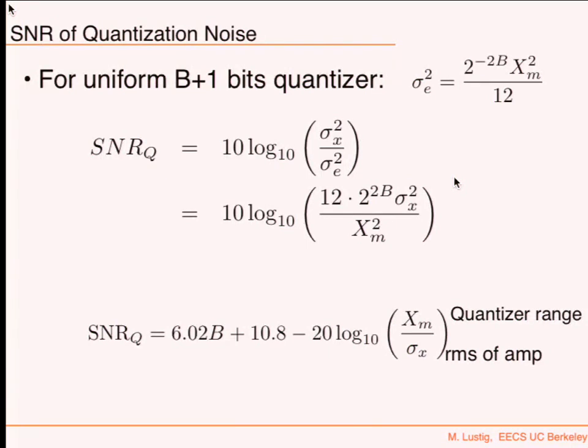Effectively, by quantizing the signal, you're adding noise to it. Crazy, right? But the cool thing is we can calculate how much noise you're adding. For a certain SNR that you're capturing, maybe you don't want to quantize more than the signal-to-noise ratio already in the original signal, because that would be wasteful.